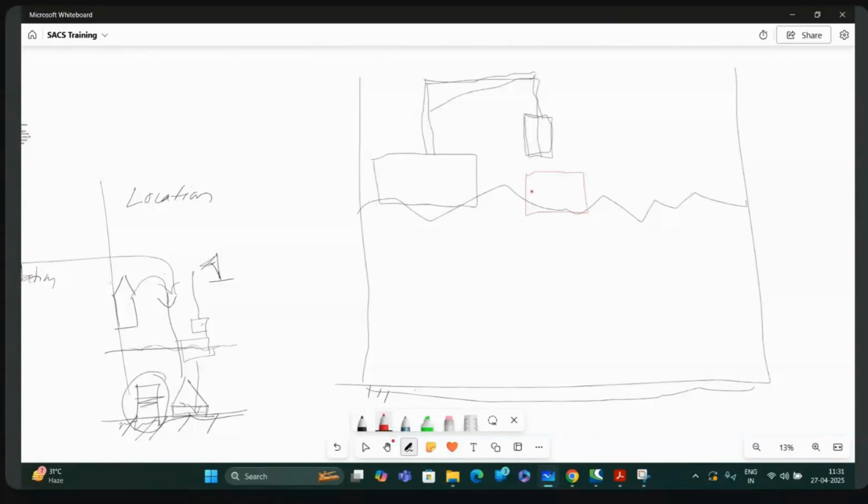The structure will have more forces because the waves are hitting, the wind is there, and there will be slamming as well. Slamming is when the water hits the structure from the bottom. This will create instability for the crane. So it's very critical. This is called the splash zone, and we call this operation splash zone crossing.